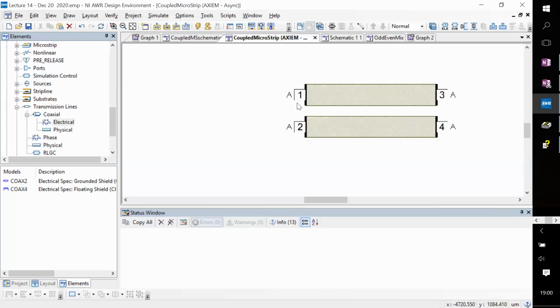And a directional coupler is a 4-port device, and it has this property that if I send a signal on 1, a large fraction of that, something like 99% of the power, will end up in 3, right? And that actually seems to suggest that, oh, this is just basically a straight line, it's just going there. But 1% of the power goes to port 2, and 0% of the power goes to port 4, which is again called the isolated port.